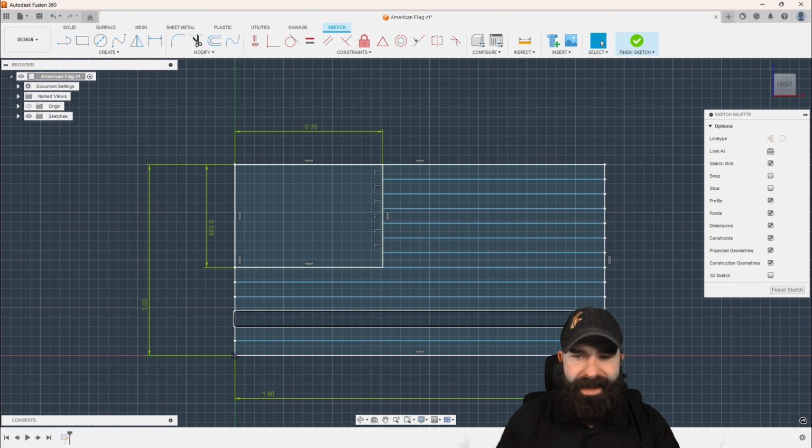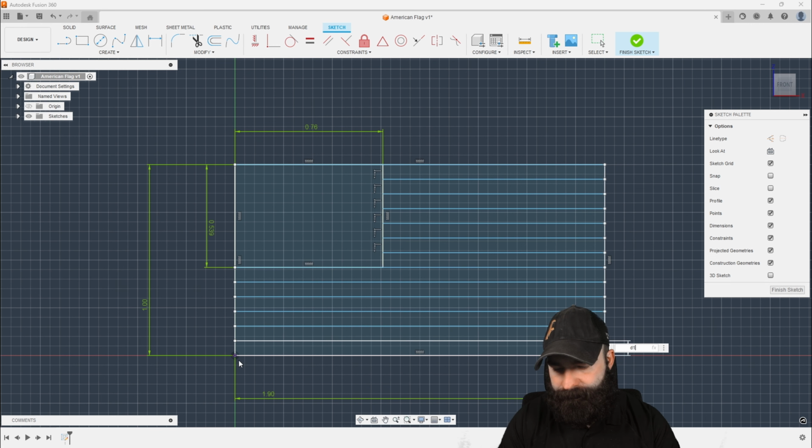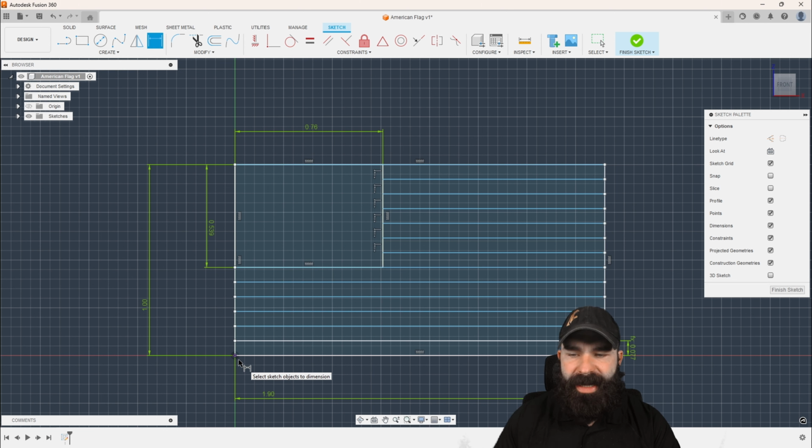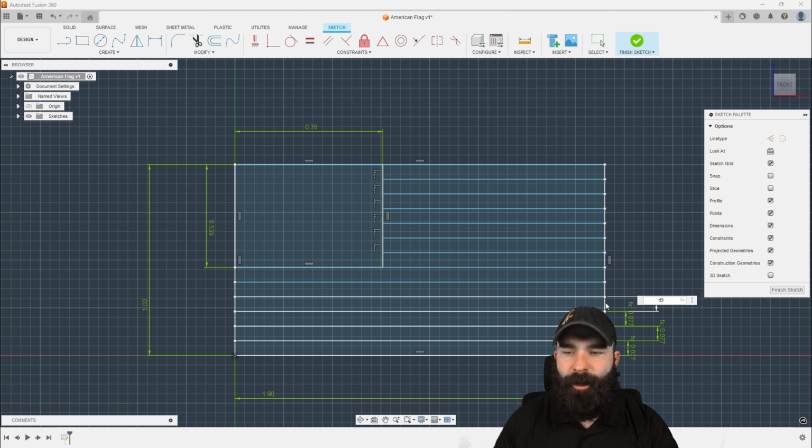But now that I have the lines, let's add our dimensions in here. So I'm going to dimension the first line off the bottom. And that dimension is going to be dimension 1 divided by 13. What that's going to give me is that fixed dimension. It should be 0.76. We're getting 0.77, but that's more than okay. So as we go up the line now, I reference that back, and that's how I'm going through this: I go to each one, and I click the one before it. You could reference each and every one of these to the very first dimension if you wanted. However, at the end of the day, the only thing that matters is that in my case, D9 is always going to be that first dimension to control everything.